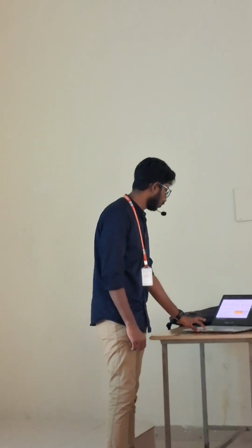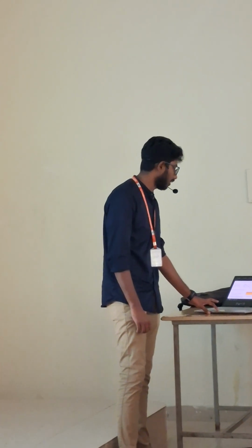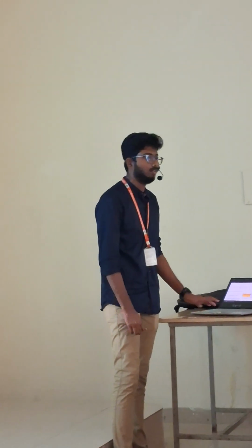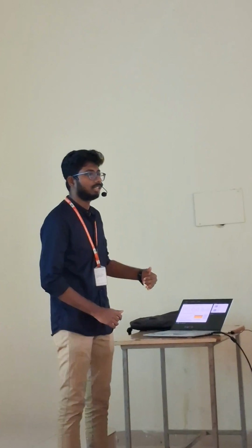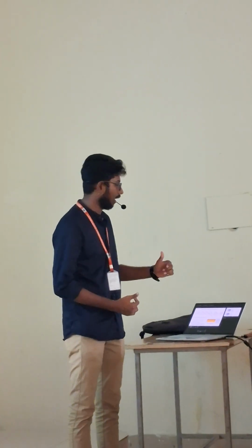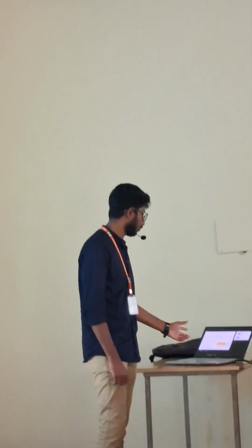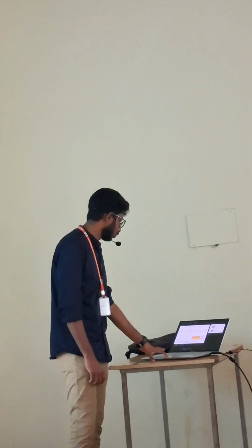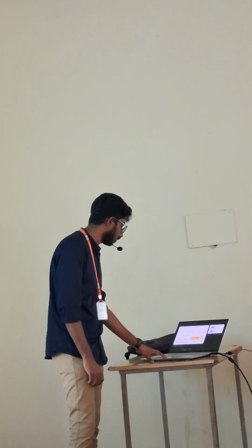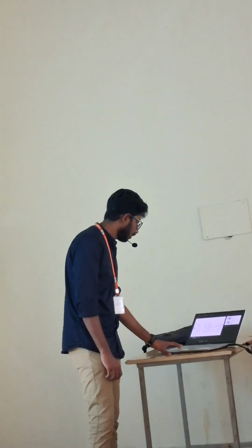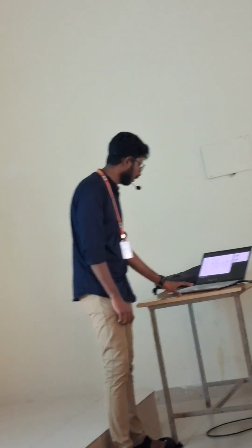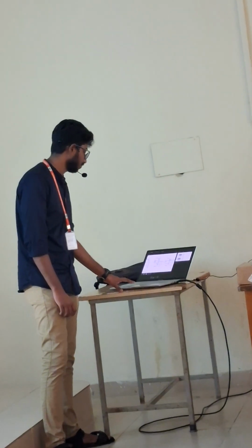The electrons from the surface states hop up into the conduction band of AlGaN, and its slope bends due to the discontinuity in band. The electrons flow from the conduction band of AlGaN to the GaN interface. This forms a two-dimensional electron gas, which is here. This is a potential well, where the electrons get accumulated.